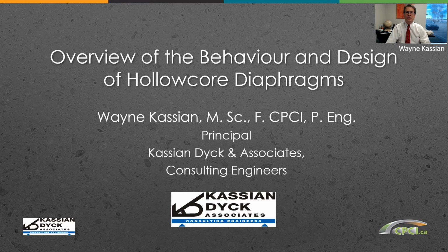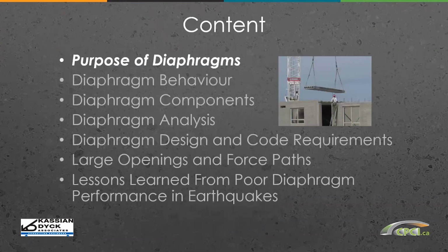I'm Wayne Kassian from Kassian Dyck Associates, consulting engineers in Calgary, Alberta, and today we're going to be talking about Hollowcore diaphragms. In this webinar, we're going to be discussing the purpose of Hollowcore diaphragms, diaphragm behavior, looking at different components in the diaphragm, diaphragm analysis, code requirements, how to handle large openings and look at force paths, and lessons learned from past earthquakes.